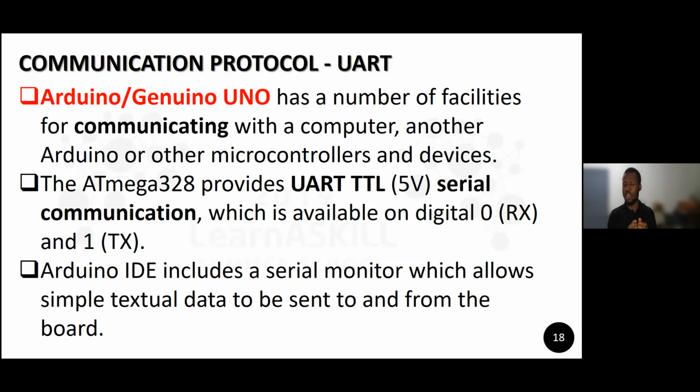You will have to remove the Arduino from your circuit, connect it to the computer, and load your code before you insert it back into the project and package it. You always have to remove your Arduino from the project and load your code before you insert it. This is because when you do that, there is a conflict between the USB and your circuitry.